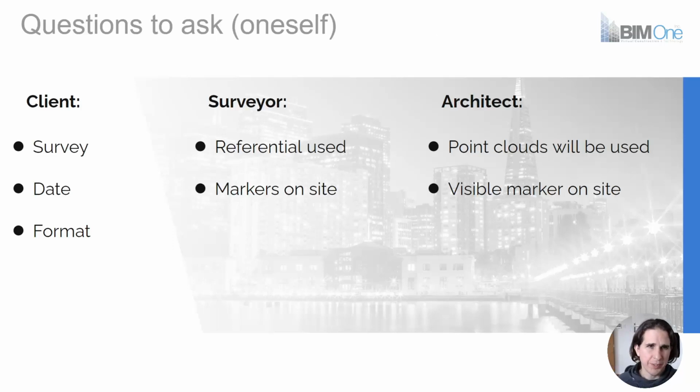There are a few other questions actually that you could ask yourself. Are the scope of the project and the road access included in the plan? Are the level surveys sufficient to represent the complexity of the terrain? Or do you need basically a triangulated topography from Civil 3D, for example? So watch out for the point cloud coordinate system versus the survey plan. A common reference point will be necessary.